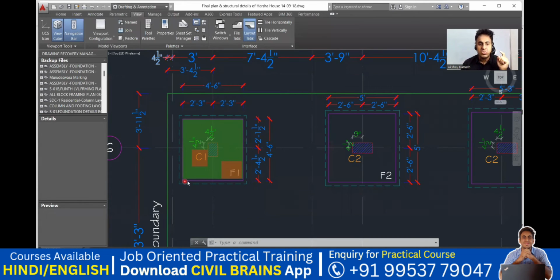It is mentioned here. So this size is actually 4 feet 6 inch, and this is also 4 feet 6 inch. This is also 4 feet 6 inch. Got it? So the size of my footing is 4 feet 6 inch by 4 feet 6 inch. Here you are not going to get the depth of your footing.